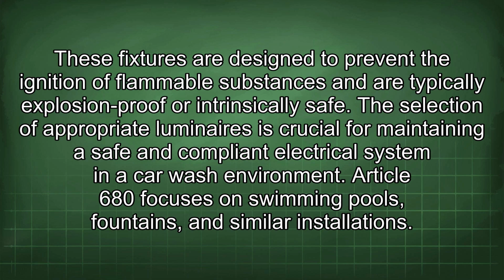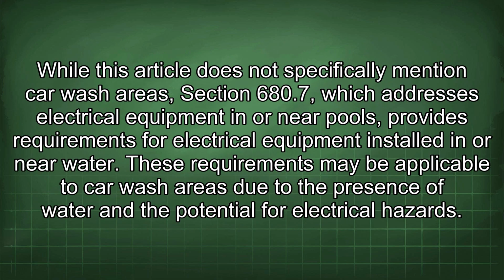Article 680 focuses on swimming pools, fountains, and similar installations. While this article does not specifically mention car wash areas, Section 680.7, which addresses electrical equipment in or near pools, provides requirements for electrical equipment installed in or near water.